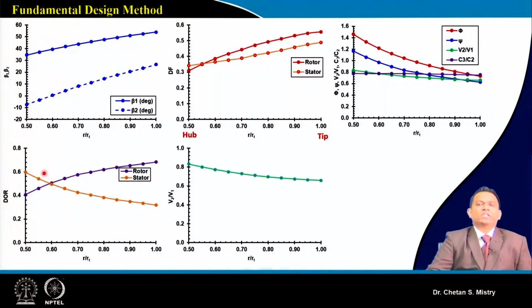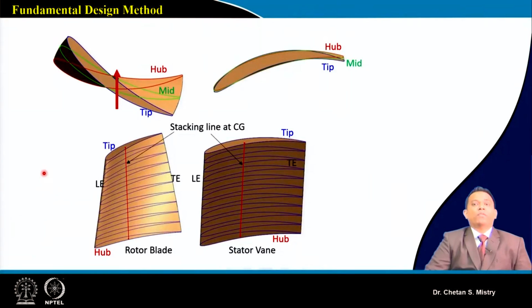Now this gives us the idea about the calculation of all flow angles, and based on that we can assume our aerofoil to be C4. We now understand how to calculate the x and y coordinates for the aerofoil for the upper surface as well as the lower surface. Since we are using the C4 aerofoil, we know the CG point and our stagger angle, and based on that we can do the calculation here. Okay, and we can generate our geometry.